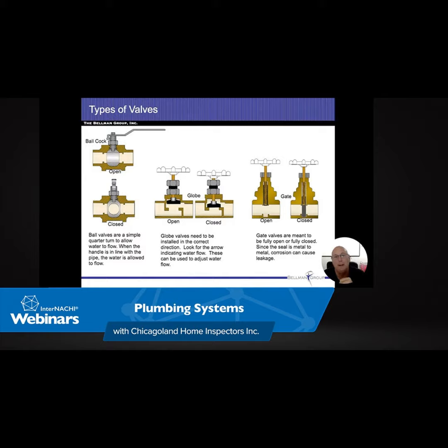All right. Galvanized has been common, even though it rusts and corrodes on the inside. It does have the same threading, and that's something that's been time tested for long periods of time. But it does have a shortened lifespan. That's 60 years. This is a water supply line, and you can see the black pipes on there. Those are the black iron pipes, where the more grayish ones are going to be the galvanized.